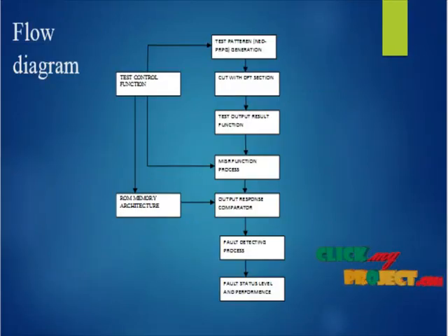In our process, we give the input for the test parameters generation. In the test parameters generation, we give the built-in self-test schemes, the solution for testing the VLSI process. BIST is used to make integrated circuit manufacturing tests faster and less expensive. After that we use the CUT with the DFT section. In these sections, the main purpose of the BIST is to reduce the complexity and thereby reduce the reliance on external